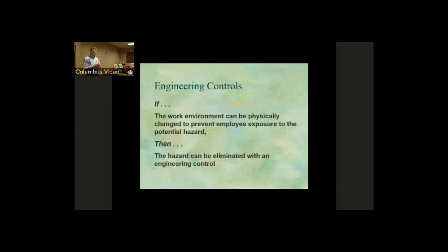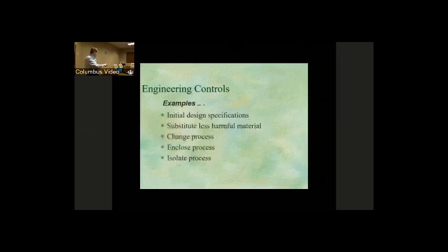Engineering controls consist of basically, again, ventilating the area. You know that if we're dealing with hazardous chemicals, it could spill, so using spill control pallets in there. Isolating the areas, isolating chemicals so people aren't exposed to them. So again, change the employee exposure to the potential hazard, and then eliminate the hazard through engineering controls where necessary.